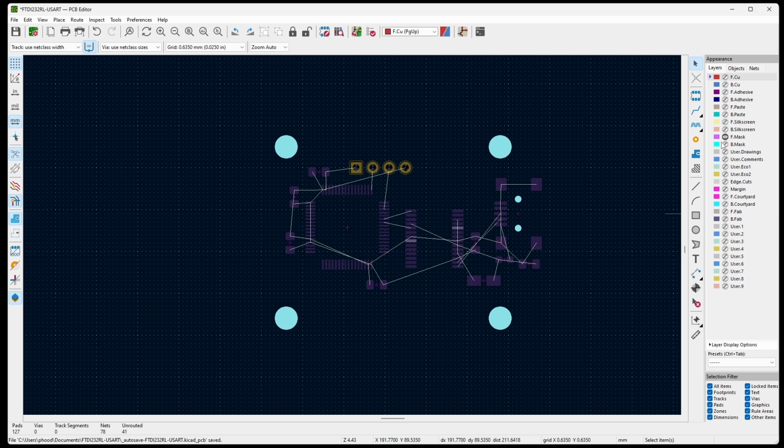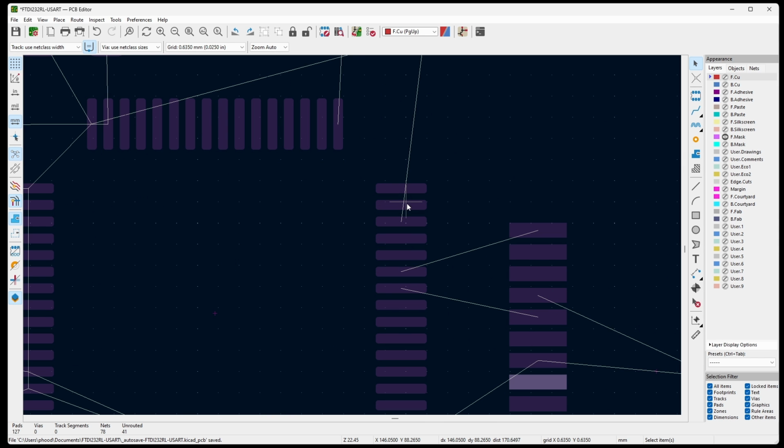The solder mask will show where solder will be laid down. When you're soldering, you want all the spaces between the solder to be free of solder. So the solder mask is a coating that is applied that resists solder, so you minimize the bridging of two pins.